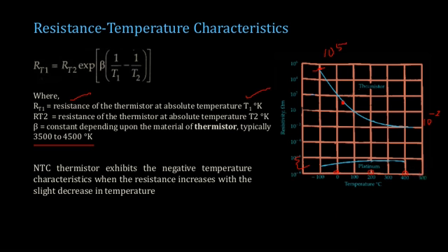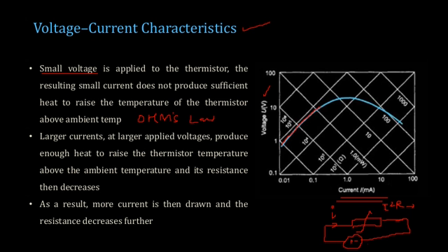Here you can see that after your resistance is now coming to a steady state, you have a constant region here. In the same way, your resistance is coming to a steady state, or the change in resistance is reduced to 0. You will have a steady state when the power dissipation is balancing with the power that is applied to the resistor. That is, you have equal power dissipation and power input, your resistance will not change further, because whatever heat is produced is released, and you have no change in temperature.